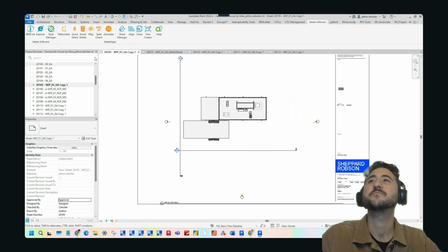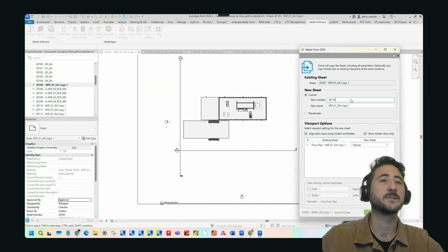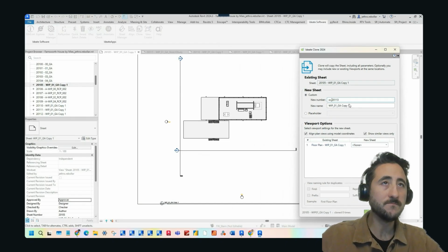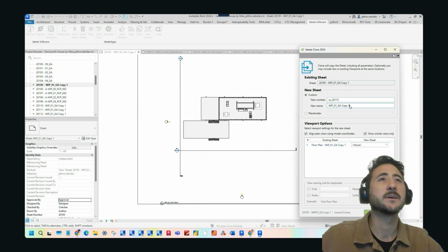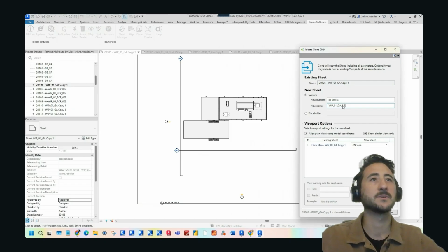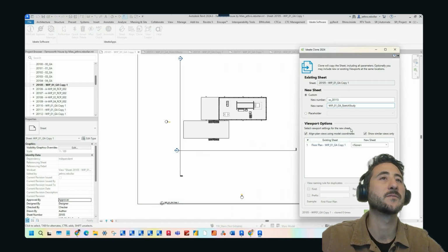And copy one. And we'll go to the clone tool and it'll automatically choose the view that I'm in, 20105. And this is the sheet that I'm copying, and let's say I want to give it a new number. Let's say I want to send it to the bottom of the pack. I'm going to call it XX because it's a study. And so that's the name of the sheet. And the new name I want to call it is Sketch Study SS. Actually, that stands for superseded. Let's go Sketch Study. Let's just spell it out for the purposes of this demo.